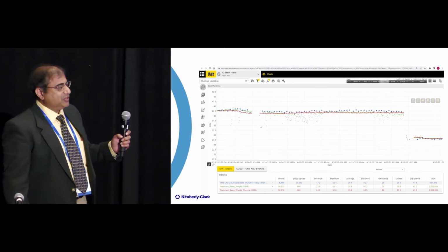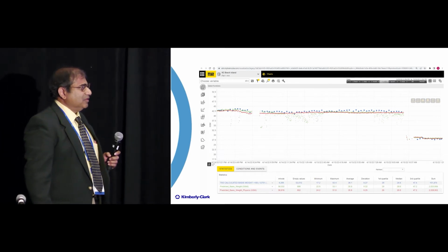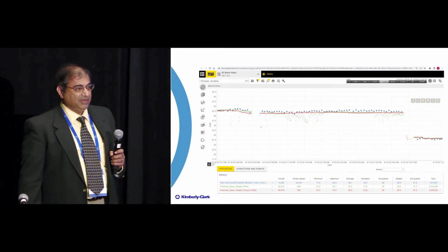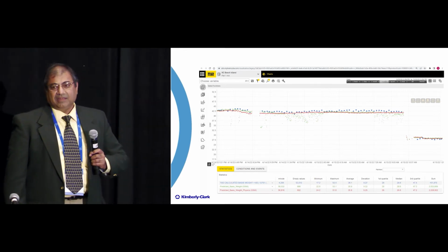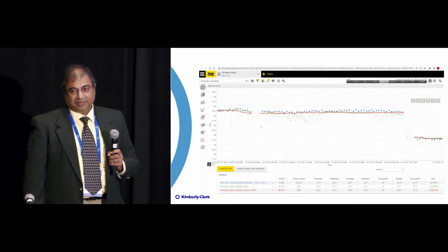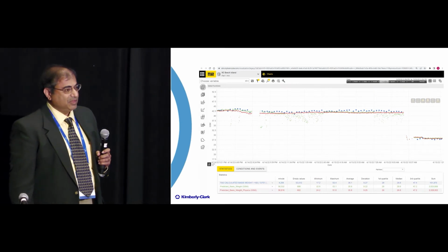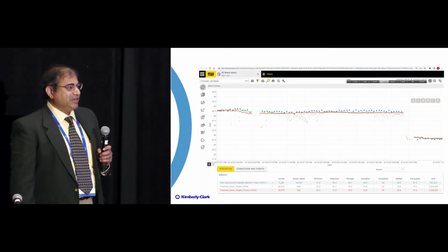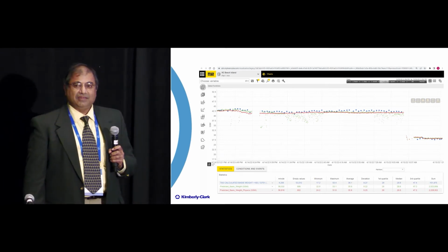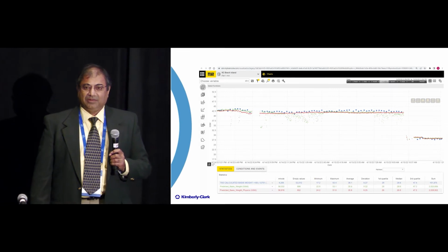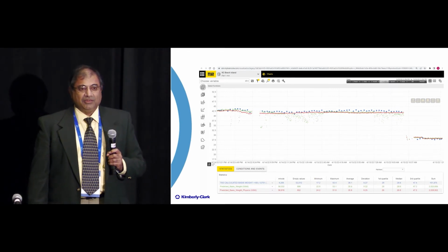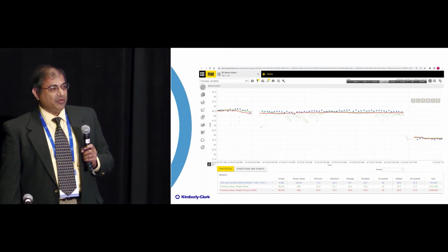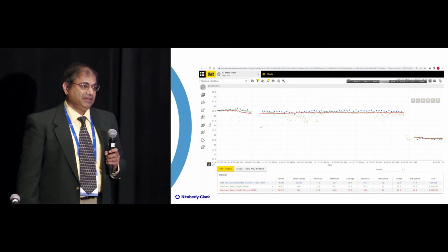So what we ended up actually doing, and I don't have a slide to show, we ended up using the physics-based model to predict the base value. And then we used a data science approach to predict the error between the physics model and the lab measurements, so that I limited the reliance on data science and I never go unstable. And I can still take advantage of simple correlational relationships to improve performance while maintaining stability.